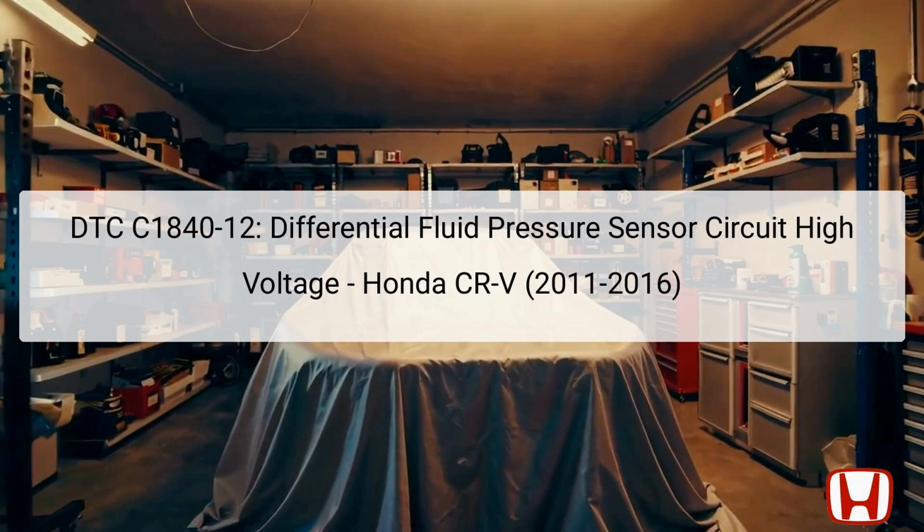When the engine is running, the sensor generates a voltage reading that should typically range below a given threshold. Should the sensor's readings exceed 4.14 volts, a high voltage condition is triggered, prompting the vehicle's onboard diagnostic system to log this code. Addressing this DTC is vital for maintaining the vehicle's drivability and safety, particularly in varying road conditions. Proper troubleshooting and successful resolution of this code will restore the functionality of the AWD system, ensuring the vehicle performs reliably under diverse driving situations.